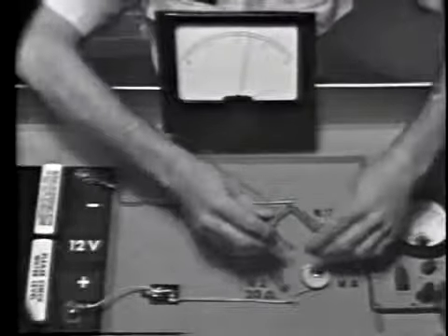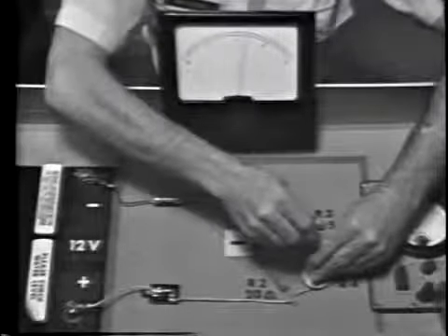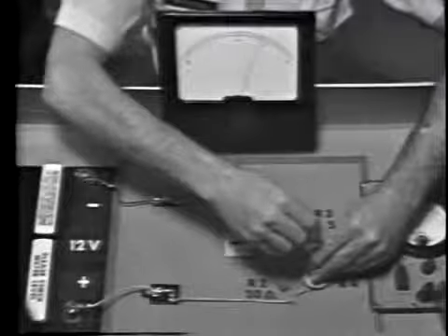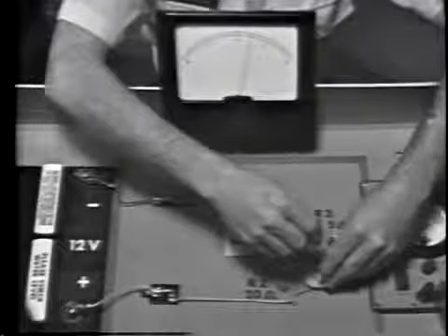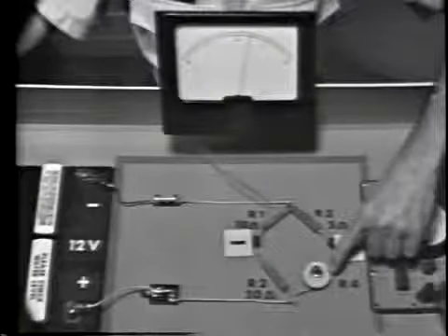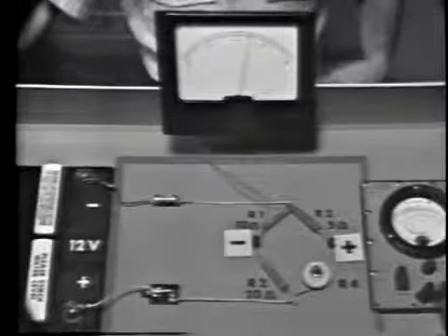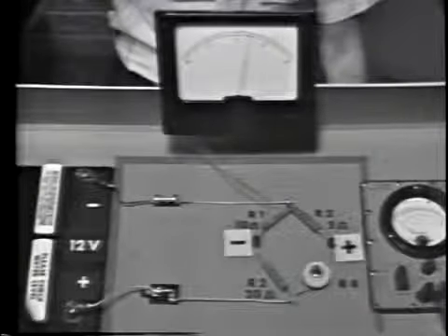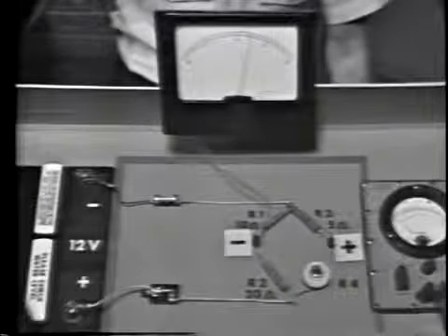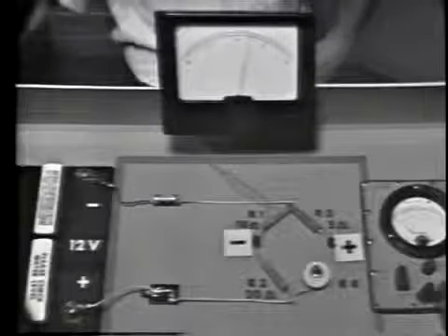So notice then that with a single control, this rheostat, we can cause current to flow in either direction across the bridge. And of course we can vary the amount simply by upsetting the ratios more. Now this feature of the bridge circuit makes it extremely valuable in applications such as weapons control systems, antenna positioning, measuring devices, and systems where a highly sensitive control circuit is required.